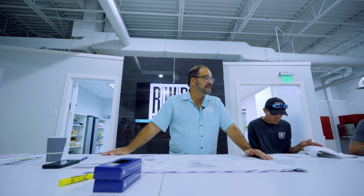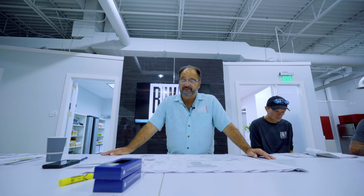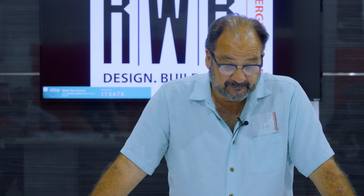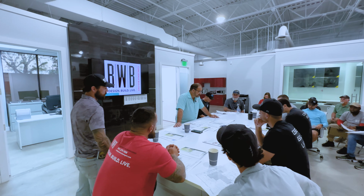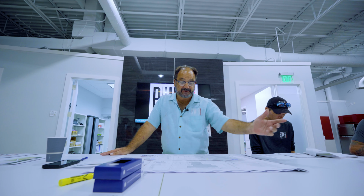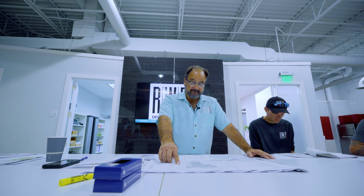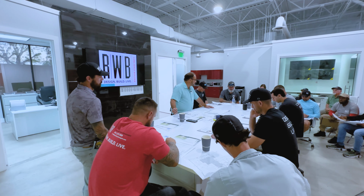He's going to calculate how much water has to be displaced by this system, and he's going to design these elements to take that much water without overflowing. In this case, he's actually designed it with an overflow, so anything that does make it through pops up and goes to the south. Oh, excuse me, in this case to the west. Okay? He's got exfiltration fields at the top, in the south, and the north. This is his design. Okay?